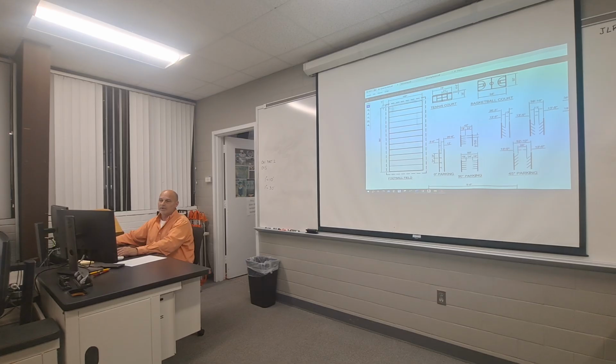So as a minimum, you need that rectangle around the outside, 160 by 360 feet. And then the dashed line around that is a no print. That is your buffer zone, your do not get in this area zone. That's for the teams, the band, the cheerleaders, everybody, the managers. That's where that's at inside there. Kind of small, but we're gonna go with that. So all the way around there, 15 feet, I would recommend you just draw a rectangle for the football field, offset it 15 feet to make sure that you don't infringe on that easement.